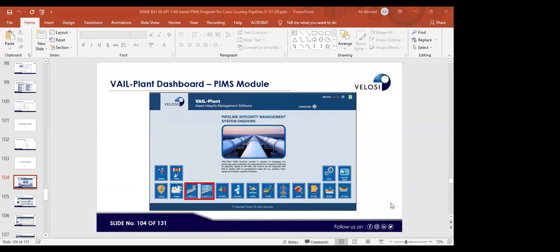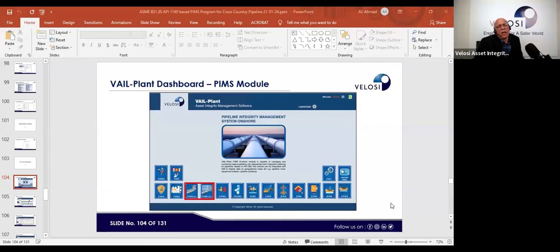Let me give an example. Take vessels which are internally inspected, and that inspection is done after the PTW system is followed. The vessel has been emptied, then cleaned, purged, and made sure there's no hydrocarbon gas. As a follow-up of inspection, if there is some metal loss, weld overlay is done internally. It means that kind of welding is acceptable. Same is the case here.